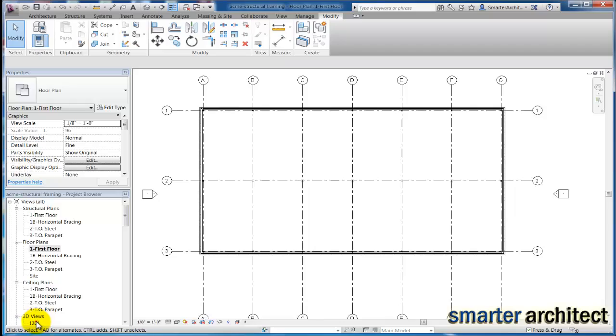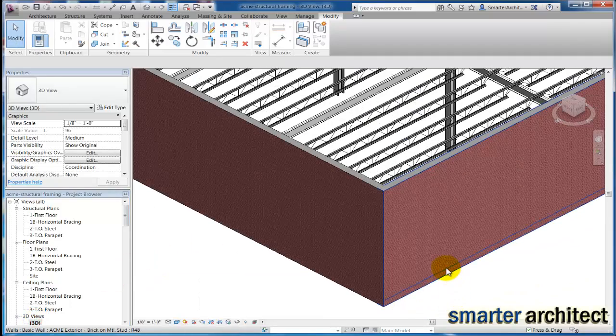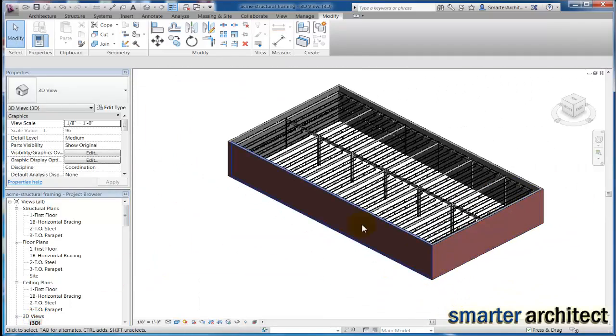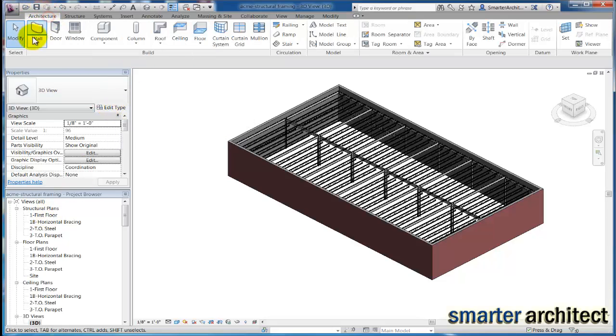And there you go. We've set up our initial wall type that we need here for our exterior walls. And we would repeat the process for our interior walls, just taking a look at the components that would make them up. Remember, you begin with duplicating a wall type that most closely reflects what you're looking for, just to minimize the amount of modification you have to do once you get into your edit type properties menu for that wall.